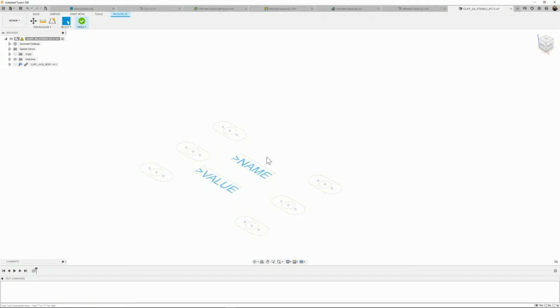The 2D footprint I can start with in the 2D PCB library, and just lay out the pads. I could use an IPC wizard that's built into this for different kinds of things. It'll do the 2D footprint and the 3D together. But for things like connectors, I'm going to start with the 2D footprint layout according to the datasheet and the pin positions and everything. But the cool thing is I can then derive a package from that, and it puts me in this mechanical modeling workspace.